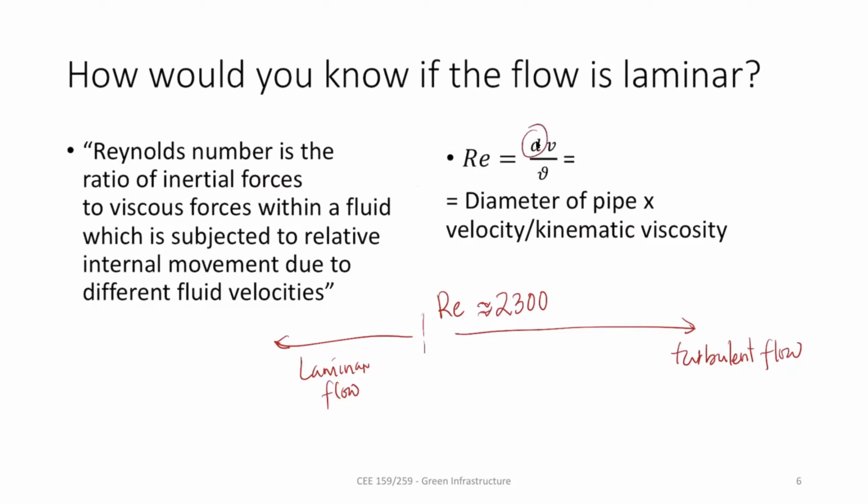This is very important. The reason is if you have a larger pipe, the Reynolds number is going to increase, or another way to say is the inertial force will be higher, and you have to think of what's the reason behind it. Let's have an example: if you have a larger pipe, let's say d is 10, and let's say d is 5, half of it.